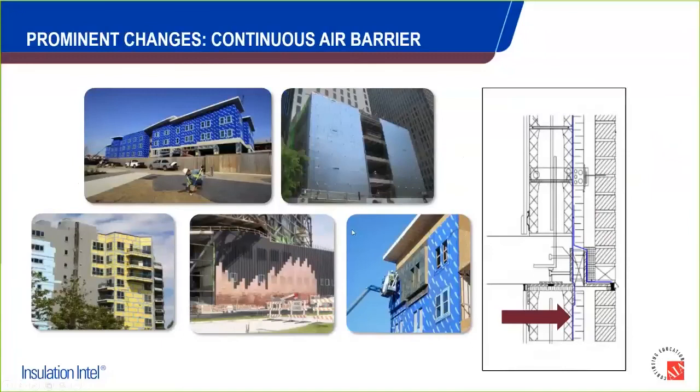Air barriers, again, the requirements driving air barriers throughout the U.S., especially in certain criteria. These, once they get over 40 feet, become a trigger for these assemblies. Under 40 feet, there is a recognition of the fact that this is a very minor combustible element, and this line right here and this flashing material under 40 feet is not sufficient to trigger the requirement.